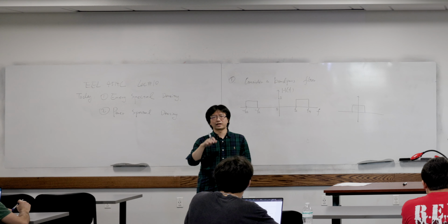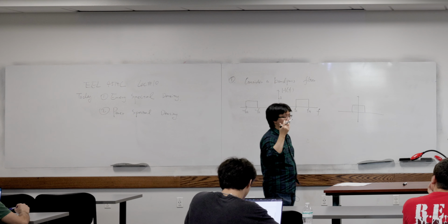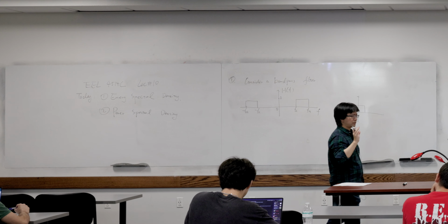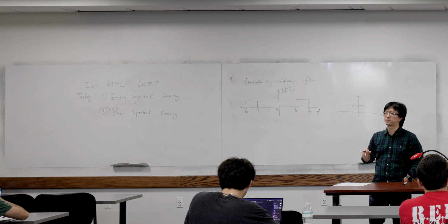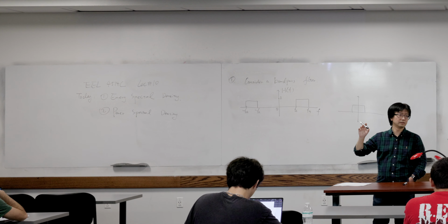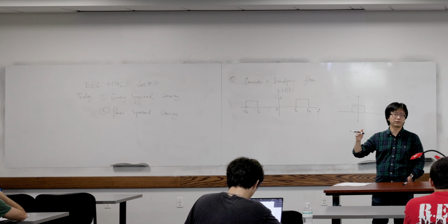If you remember in your lab 1, I think in part 2 or part 3, probably part 2, you didn't do the integral. What you do is use the signal, multiply together, and pass that through a low-pass filter to get Fourier coefficients. Is that right? So why do we do that? Why does it work?